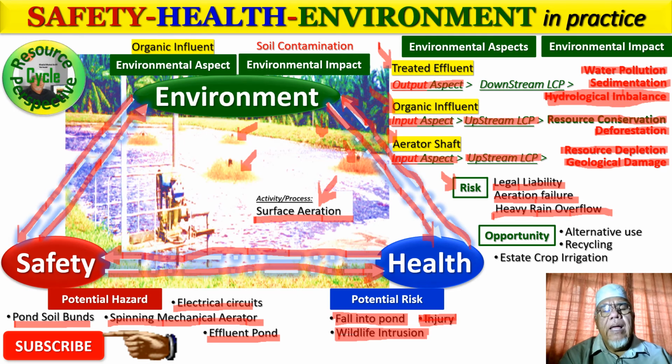That is another potential risk. Has it happened? Many times before, especially in the last 10 years. Is it a problem? Yes. All these nutrients from this pond and also pollutants in the form of scum, and also the agitation would cause some of the sludge to surface out due to the displacement effect of surface runoff.